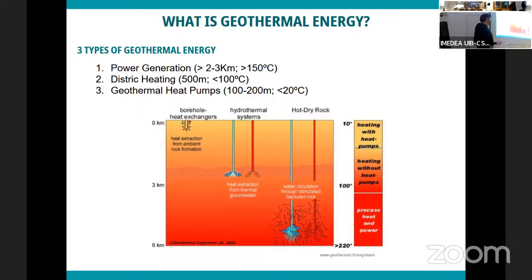But the most common nowadays is shallow geothermal, where we drill 100 to 200 meters to find, on average, about 20 degrees. Of course, there are different places. The heterogeneity of geology means that sometimes in this range of depths we can find higher temperatures because of geothermal anomalies. Like in Llucmajor, where we have a hole that doesn't follow the regular law of geothermal gradient.